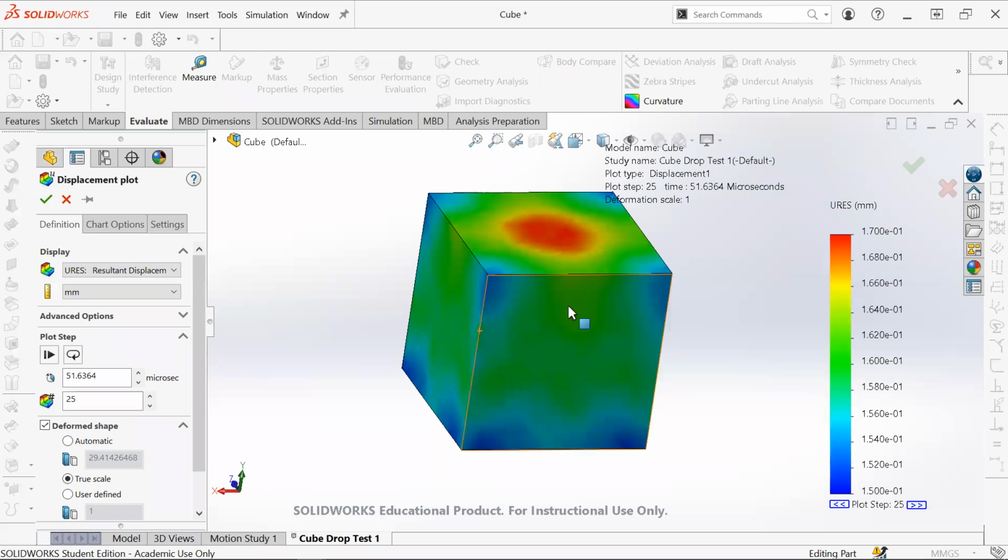If you do, it's a very, very high number, and it's not always accurate because it's very sensitive. It changes greatly as the decimal place gets smaller because stress is force over area. So as the area gets smaller and smaller, even a factor of 10 can give you a really large difference in your final, obviously, in your calculated stress.